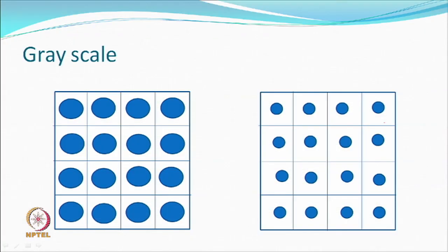So, you have variables, therefore, a print head today is able to print large drops as well as small drops. So, it may be a strategy which is software based. What do we do when we generate shades? It is quite possible that you may say, well, the resolution remains the same, in that particular area you may have smaller drops, same color, that is possible.